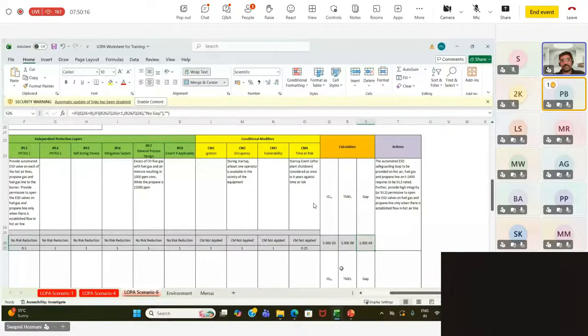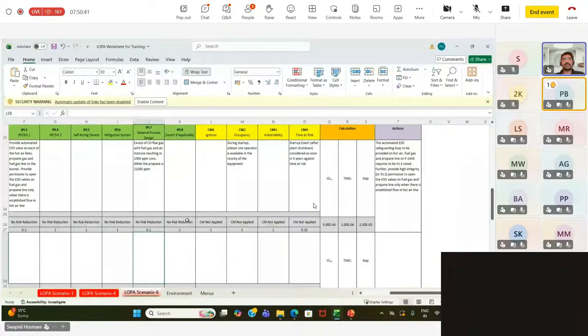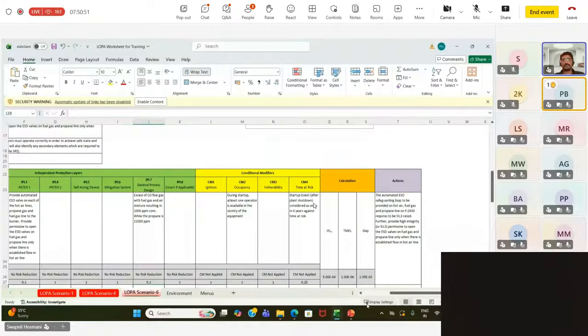Secondly, just because of this, the client insisted that we guarantee that this scenario will not be possible, because it never reaches that LEL level for propane, which is 21,000 ppm, and the resultant mixture based on their heat and mass balance was within 1000 ppm. So that is the reason we considered this as 1, and that is how we get SIL 3. Otherwise, it would have been SIL 4, and they would have to redesign the whole system. That is why they were also annoyed, and then we had to accept their rationale that this is a credible safeguard.